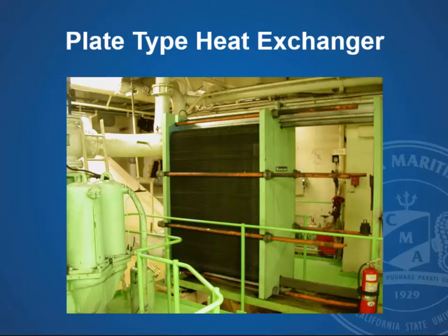One thing of note, whenever you are going to do this procedure, always measure the distance between the backing plates all the way on both sides around its circumference and jot down that dimension. One thing that can be a problem with these coolers is once you've taken it apart and cleaned each one of those plates and you're putting it back together, you want to squeeze the plates back to that dimension, as where you took it apart. If they're too loose, they'll leak. If you tighten them too much, you tend to squeeze those gaskets, it'll leak also. So always put it back as you found it.